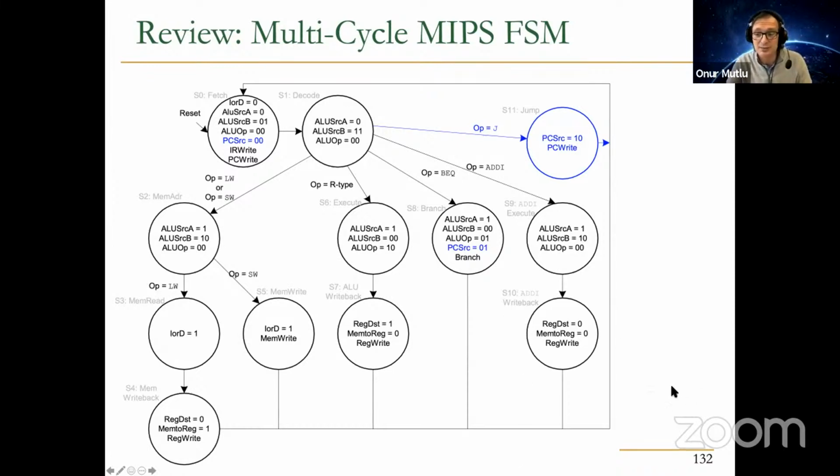So you can see, I think there's one question. What is the bottleneck for the cycle time in the multi-cycle system, this system? Basically, the answer is your creativity and careful engineering is the bottleneck in the end. And also some physical limits like register setup and hold time and the sequencing overhead. You can basically set your clock cycle time to as large as you want it to be within your design point and goals, and try to achieve that goal by changing your finite state machine, essentially.